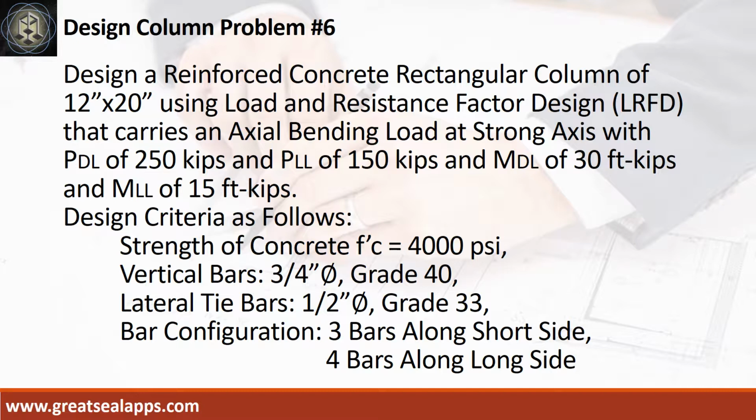Design a reinforced concrete rectangular column of 12 inches by 20 inches using load and resistance factor design that carries an axial bending load at strong axis with axial dead load of 250 kips and axial live load of 150 kips and moment dead load of 30 foot-kips and moment live load of 15 foot-kips.